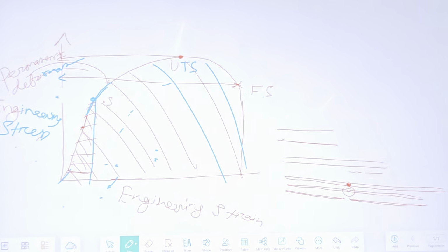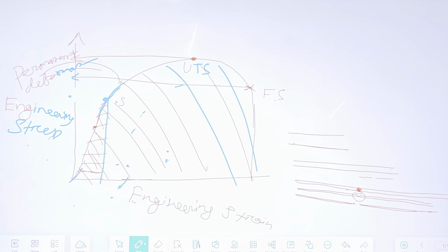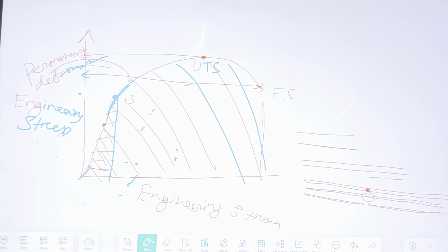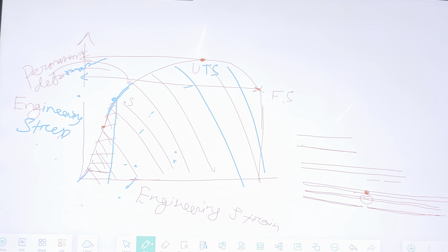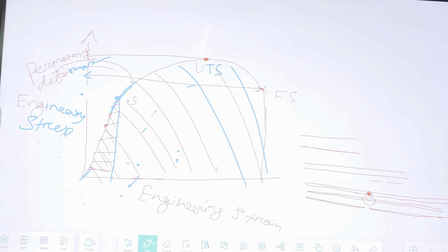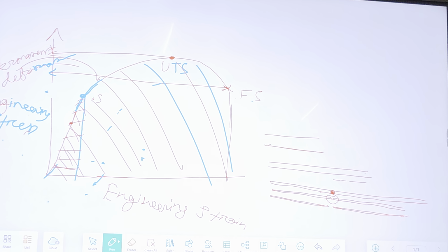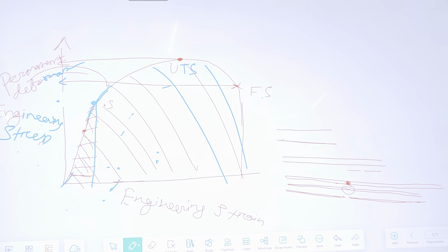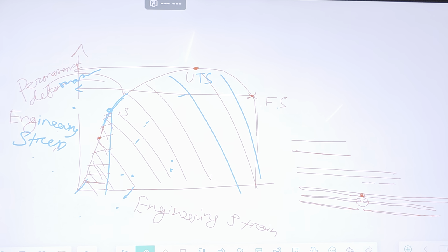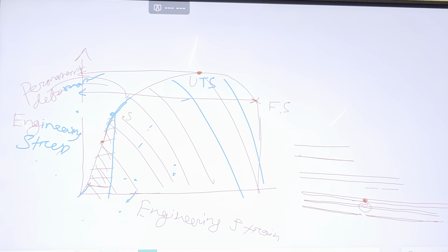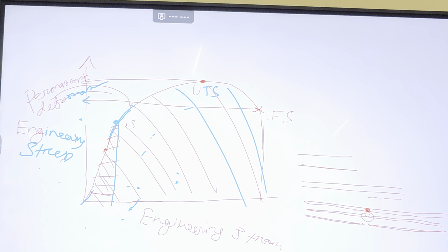Okay, and the point. So, suppose this is a stress versus strain curve for aluminium, for example. Very ductile. Aluminium is FCC, very ductile. Copper is also. But if you are talking about mild steel now, the stress strain curve will remain the same or it will become different? It will become somewhat different. Okay, fine. But if it is aluminium, for example, it is FCC, can we really determine the YS by doing a simple tensile test?